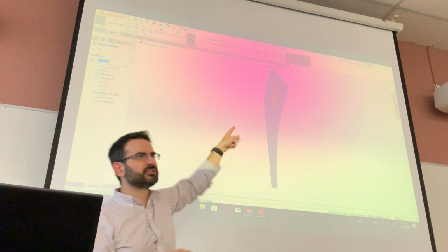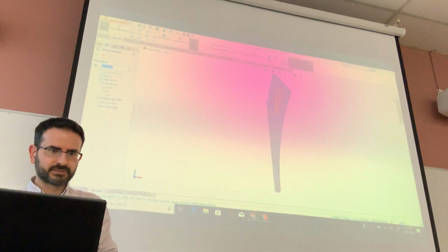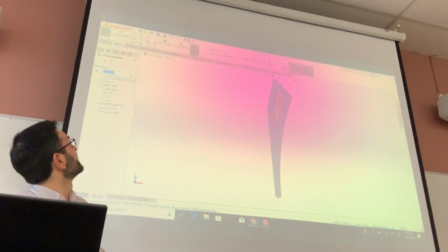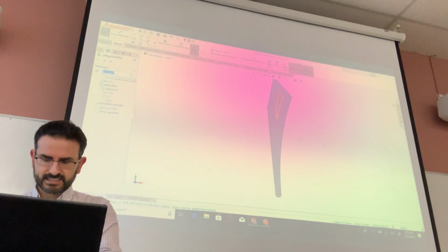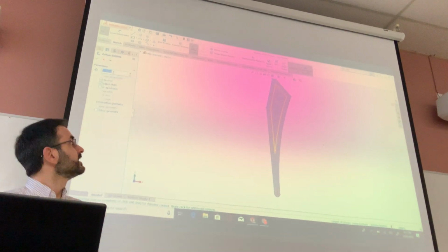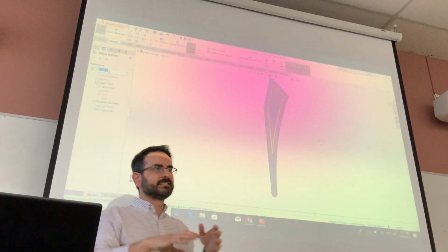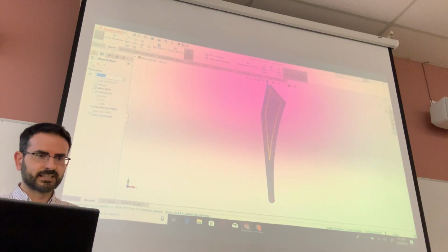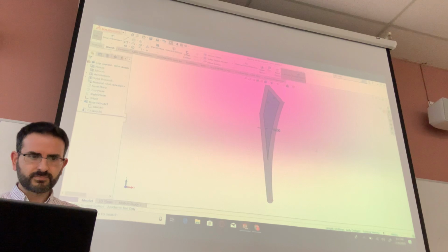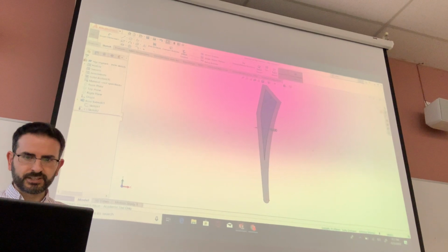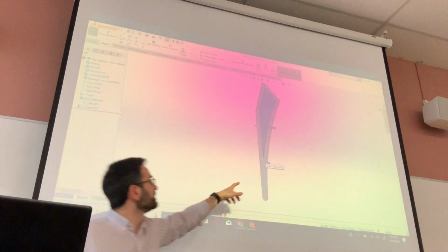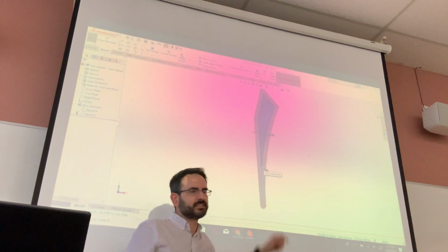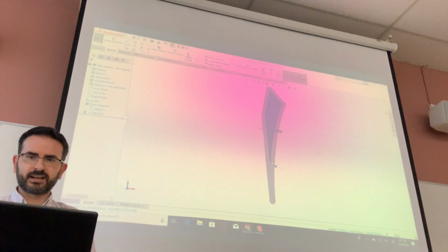Now that's a little bit too small, and that's because the offset is set by default at 10 millimeters. Let's make this 5. So now we have a nice carving in there. So I'm happy with this. So I say okay. One more thing that I can do here is that I can try to avoid these super sharp corners here that are also difficult to manufacture.